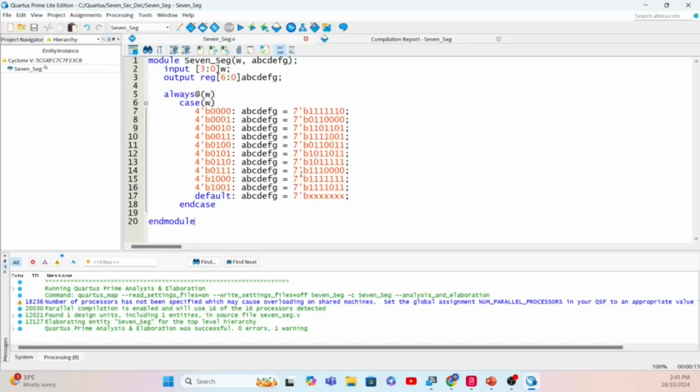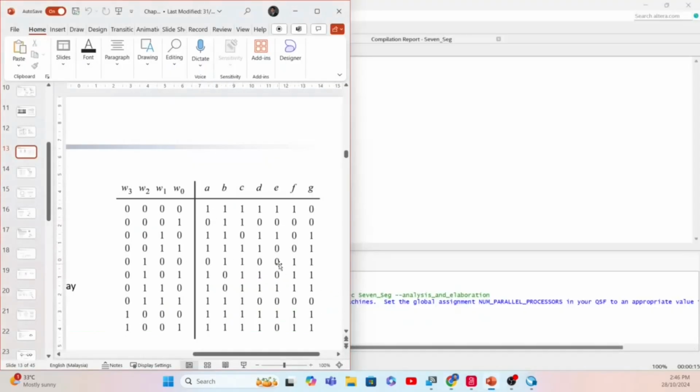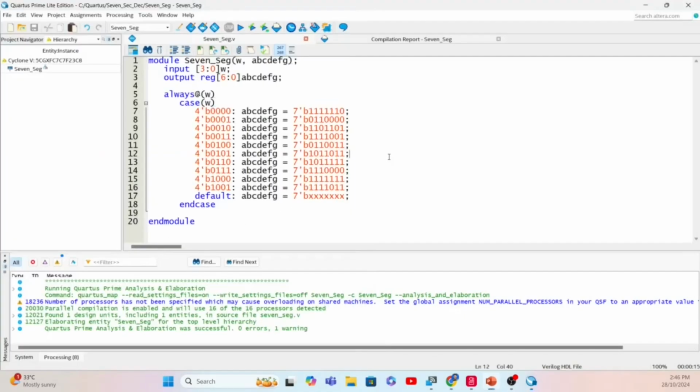So it looks like the design is okay for now. We need to verify whether the design is correct based on our specification. In our case, we need to see that the output of this design, when we give the input like this, is exactly this, and is consistent with the truth table that we have here. To do that, you need to write test code. The test code is called a testbench in electronic design.